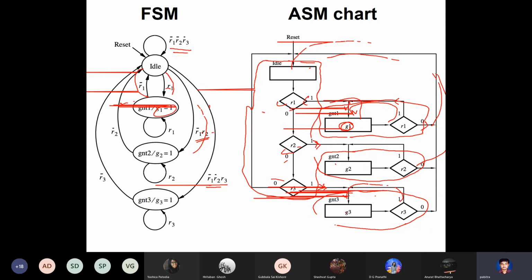But in more complex circuits, let's say a multiplier circuit or a divisor circuit, or a more complicated circuit which does blockwise operation, fairly complicated. You see, the FSMs are good for simple circuits like a sequence detector or maybe a full adder. But if you have a more complex circuit, then the ASM is a better representation. It's like a flow chart. It's like a high-level language. So it's much easier to do that.